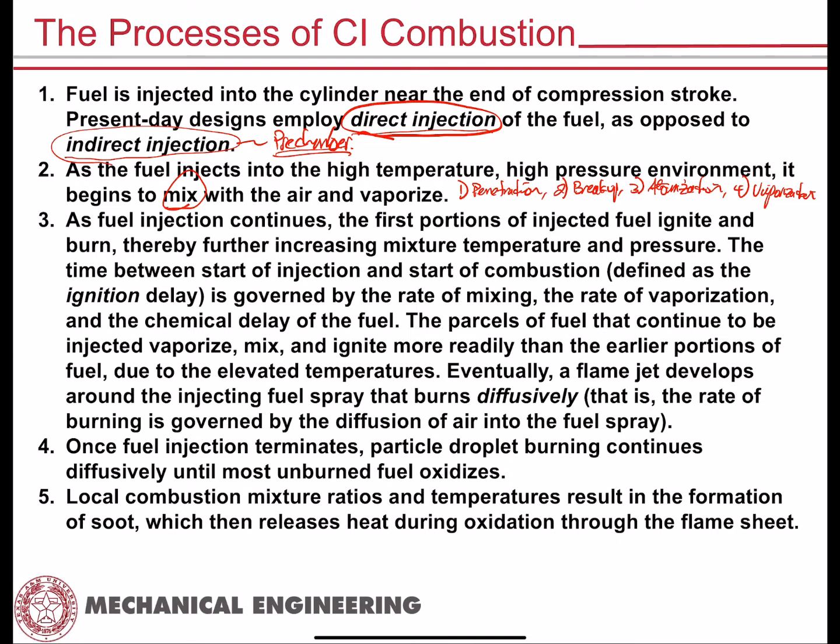And in order to most effectively vaporize your fuel, you have to atomize it to as small of liquid droplets as you possibly can. You really want to increase that surface area. Remember the Biot number? It's a little bit like that, where you want to maximize your surface area and minimize your volume so that you can vaporize your droplets as quickly as possible.